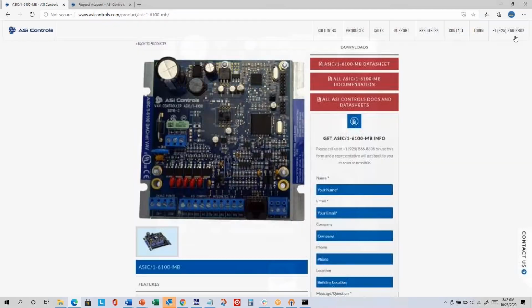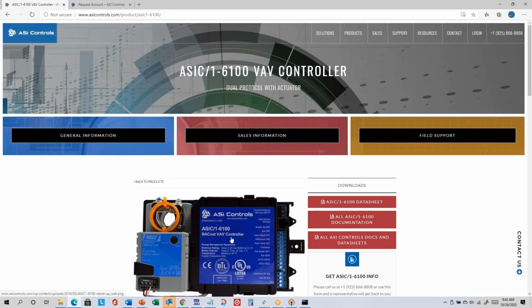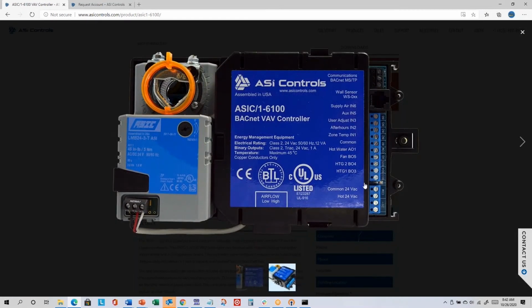And so just to kind of switch back to the Belimo package, knowing that the circuit board is sitting under here, the 3-wire connection is right here. So we just bring the wire out here and connect it to the Belimo actuator.